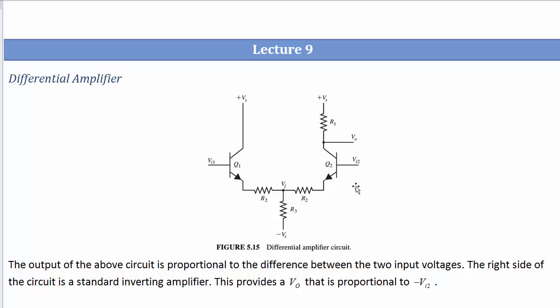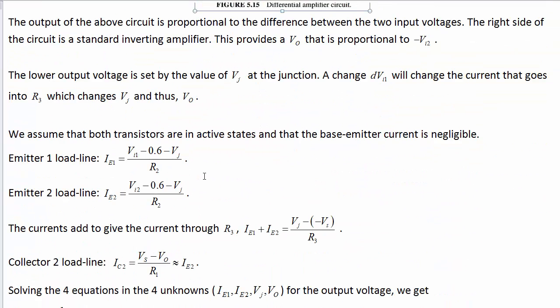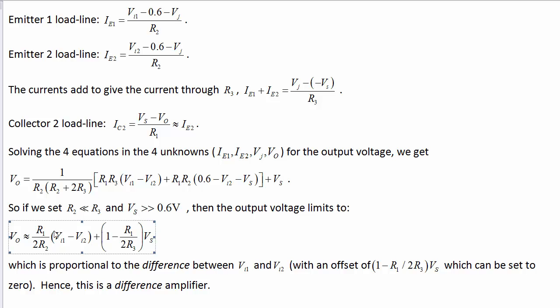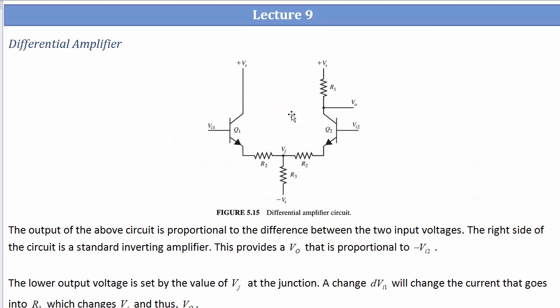This is a great thing to do because a lot of the time in the lab you've got a signal which is quite large and often has a fair bit of noise in it. But if you can take the difference between that and some other signal that should be pretty close to it, then it's much better to do that in the analog world and then analyze things in the digital world after that. So suffice it to say for now that there are going to be times when you want to have a slight difference amplified.